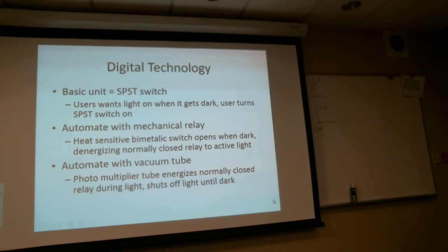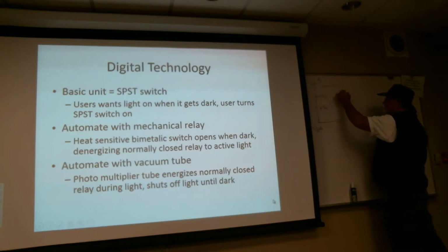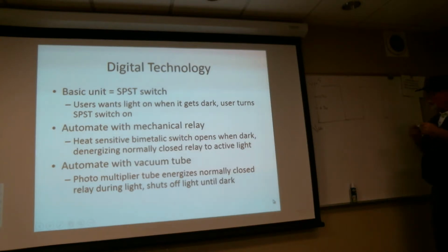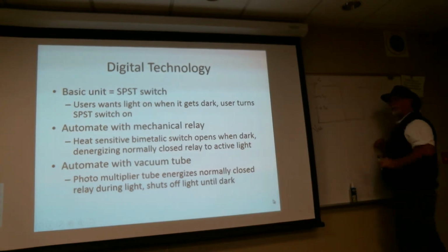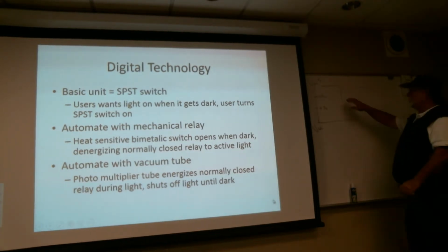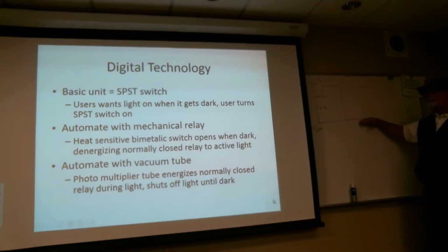And the threshold voltage can work either way. What I can do is say if I've got a digital signal that's going to come down like this, and then it's going to come up like this, and come down like this. At what point does this have to get below before we're going to call it a low, having transitioned from high to low? We could say if it goes from something above 3.3 and gets below 2.3, we're going to say it's transitioned to low. And vice versa, we could say if it's below 2.3 and transitions above 3.3, it's going to be a switch to high.